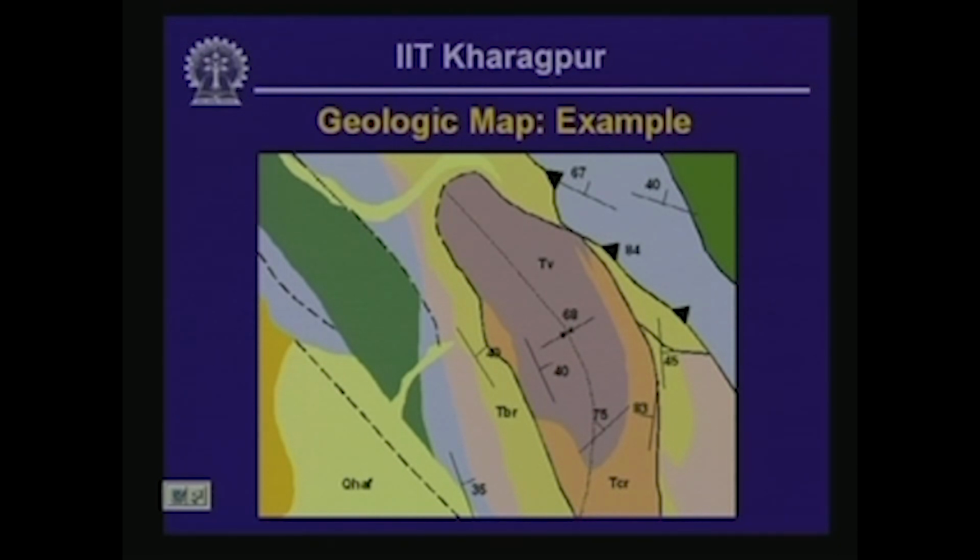In other times, particularly in important projects like a dam project or a tunneling project, the engineering geologist working for that particular project himself is going to be in charge of developing a geologic map like this to a scale which is larger than the scale of geologic maps that are normally available from the agencies that I talked about off the shelf.